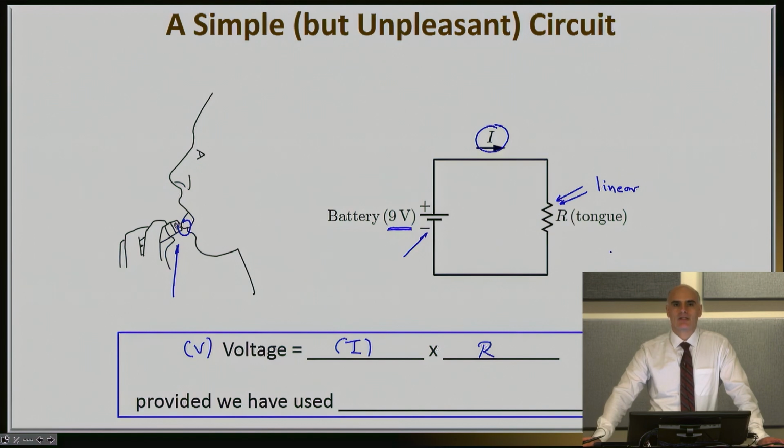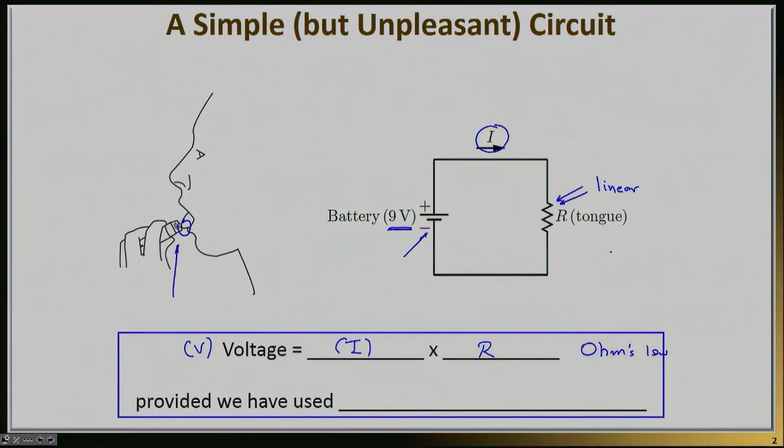And that expression that I wrote here, V is equal to IR, in most people's minds has a name, and it's called Ohm's law. And that's because Mr. Ohm actually studied this law experimentally. He was trying a bunch of different resistors, different voltages and currents, and he found out that for simple resistances that follow this ideal linearity relationship, you can write down V is equal to IR. However, I want to emphasize here that V is equal to IR is only half of Ohm's law, even though this is what sticks to most people's minds.